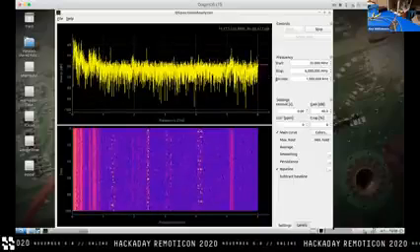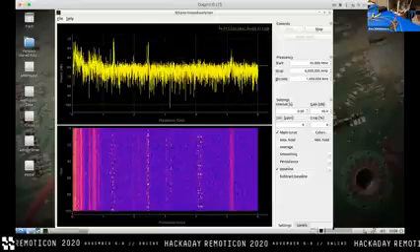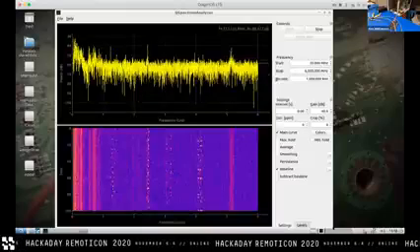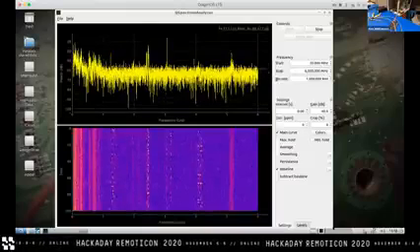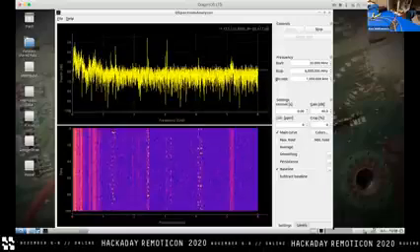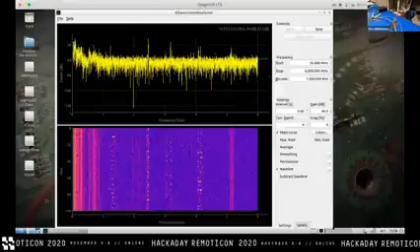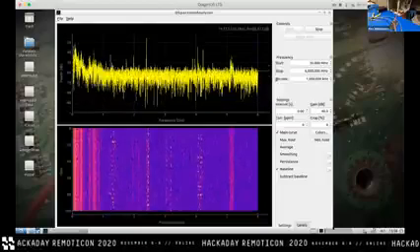And you might even be able to get away with doing that from a pre-compliance standpoint, because basically the issue that we have here is we have no idea what the power into our device actually means. The LNA isn't calibrated, the line losses are not calibrated, the antennas are far from calibrated. None of this gives us an accurate measurement.